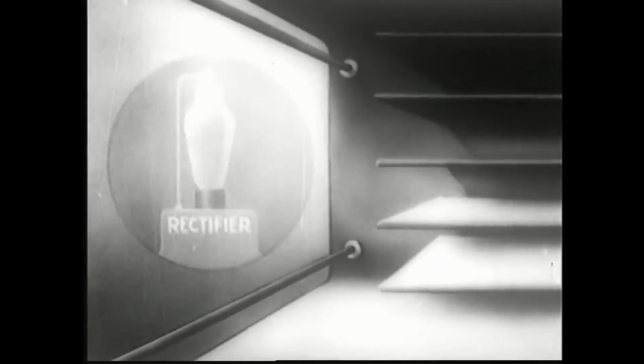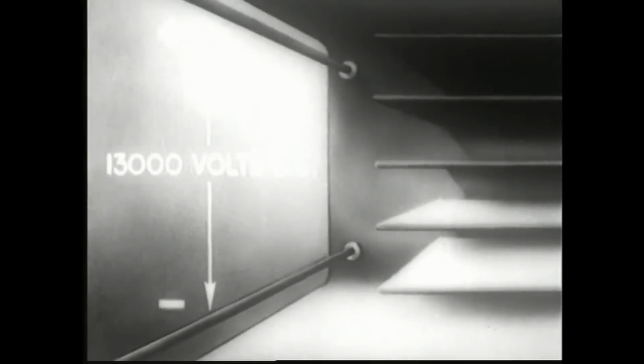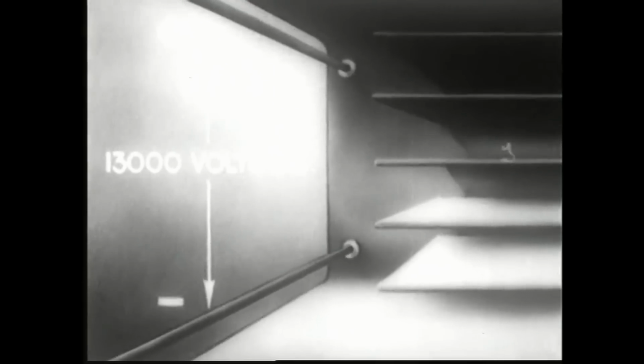Still another example of electronic rectification at work is the precipitron, a device for cleaning air electrostatically. This diagram explains how the precipitron works. The rectifying property of electronic tubes is used to apply a potential of 13,000 volts DC to tungsten wires and 6,500 volts DC to collector plates. As incoming air passes through the field of these wires, each particle of dirt receives a positive electrostatic charge.